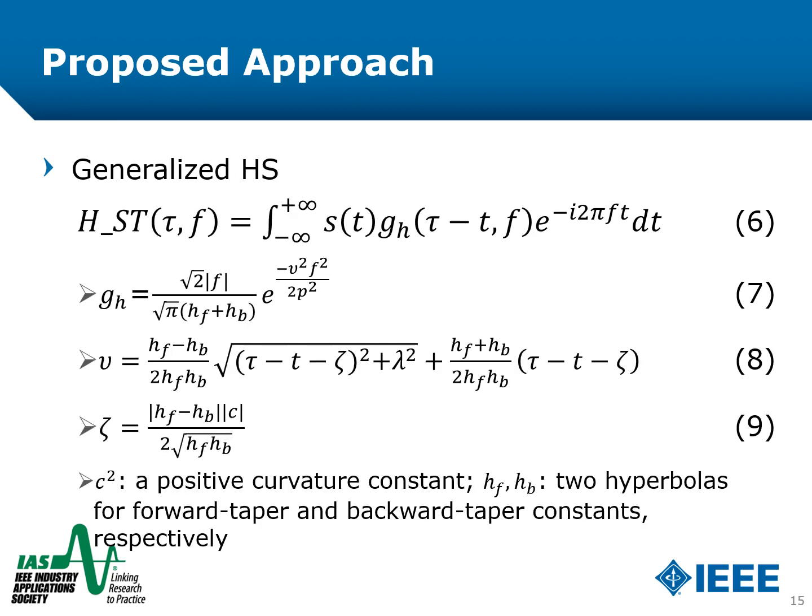Equation 6 is the generalized hyperbolic S-transform. A hyperbolic window is used instead of equation 5 to form the generalized hyperbolic S-transform from a general Stockwell transform to enhance the generalized window's resolution as high-frequency contents of fault transients. Equations 7, 8, and 9 show the detail of the elements of the generalized hyperbolic S-transform.